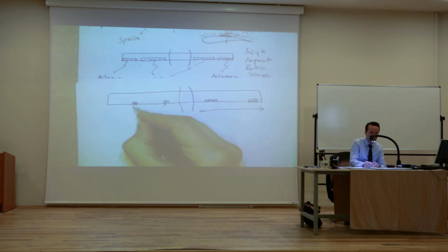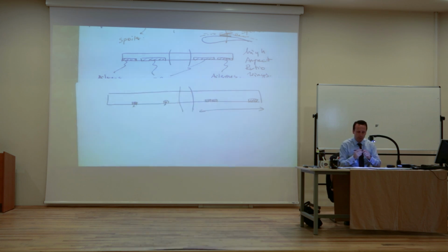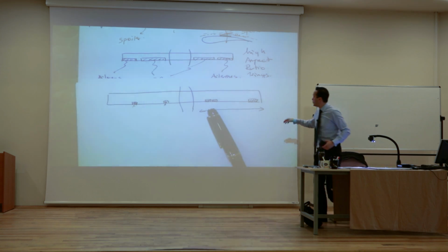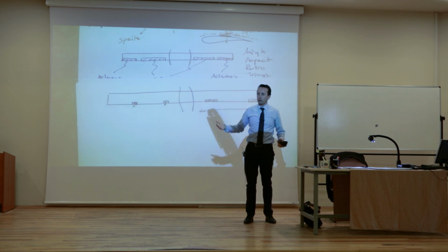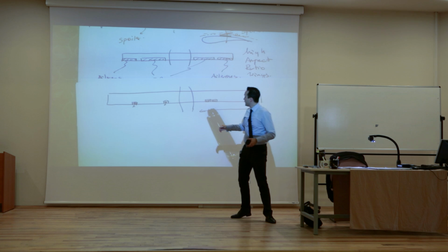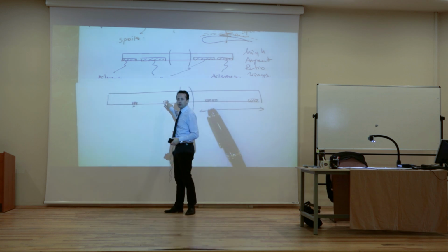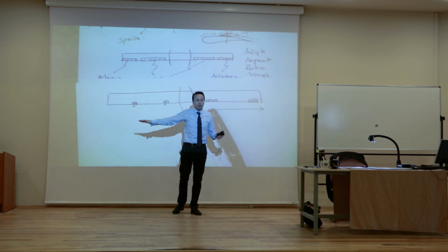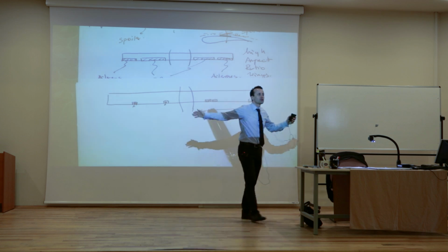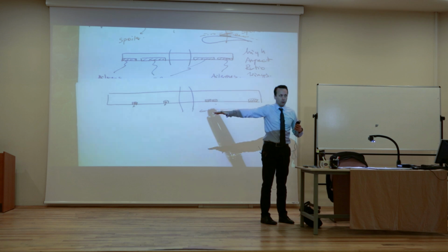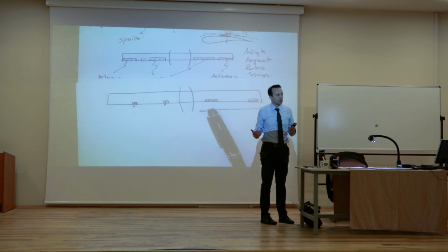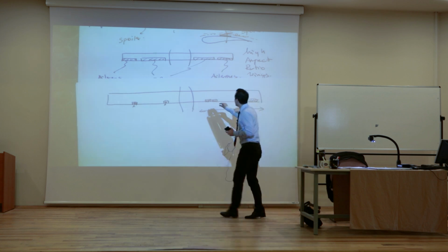Again, control surfaces, not flaps, just things that move up and down. And you wonder what these things are. Well, they can help you to maneuver, of course, but they can also help you suppress some of the structural modes, the aeroelastic modes of the wing, if you move them up and down, because you don't want the wing to oscillate too much and become dangerous. Okay?